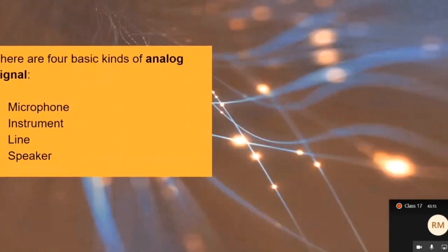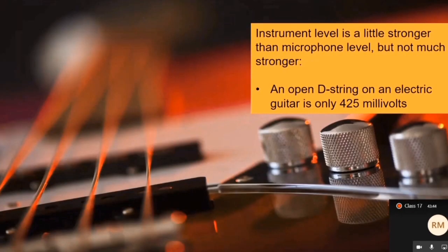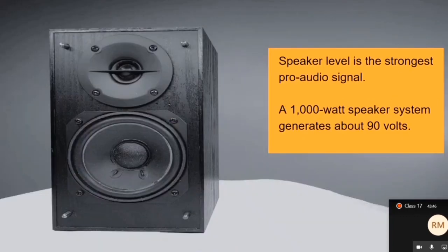So here it is in summary: microphone and instrument, very weak. They need a preamplifier to become line level. Line level, nice and medium size and strong, can be routed around your mixing board and manipulated, is then routed out to an amplifier, and that amplifier sends speaker level to the speakers. Huge 90 volts, powerful analog audio. Okay, so that's what's going on at the level of electricity and the differences between the signals.